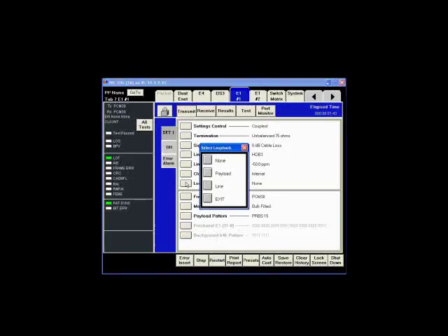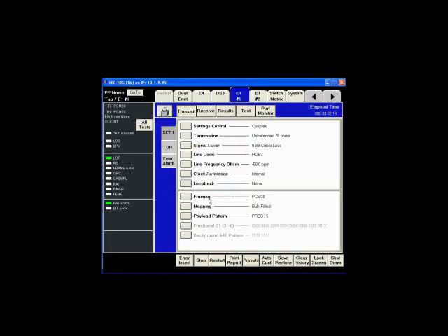And loopback, the tester itself can provide loopback. So if I put this now, it's either going to loop the line, which is the entire E1, or the payload, which is the rest of it except the frame. It actually can create a loop. Like if you had 2 test sets, one at each end of a circuit, you could put one of them in loop and then the signal from the first one would go through the test set and come back. Okay.